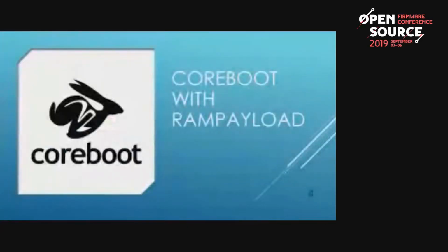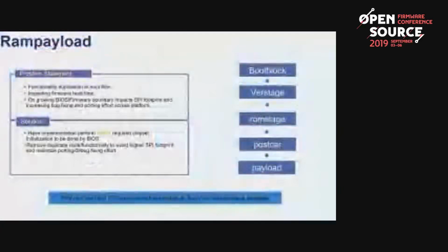So here's a quick status on that work. The observation was that there is functionality duplication in a boot flow, and that can actually impact firmware boot time. Now, for most firmware, we really don't care because most firmware burns minutes like they're going out of style. But for Coreboot, every 10 milliseconds or so you add is 10 milliseconds that you've made your boot time worse. So if you can possibly remove that kind of thing, you can get rid of it.